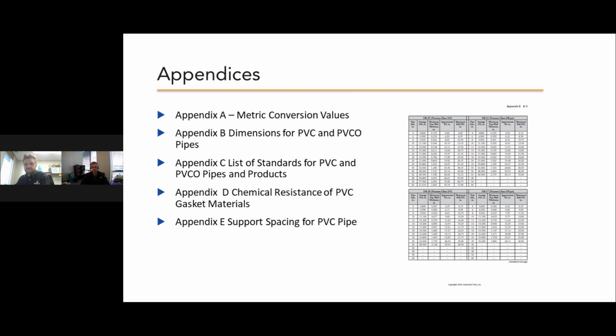There was an instance in Arizona of somebody that had left a bundle of pipe outside under a black tarp for like 2 years or something, and it did change shape because summer out there can get to 120, 125 degrees Fahrenheit, and trapped under a black tarp, it can almost hit 200 in some cases. It is kind of an extreme case, but it just goes to show you do want light colored, breathable fabric, which is more than fine, or a non-oil based paint if you're using PVC for outdoor applications, to help prevent any UV exposure. UV is not really a huge issue.